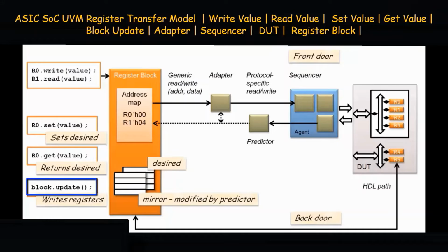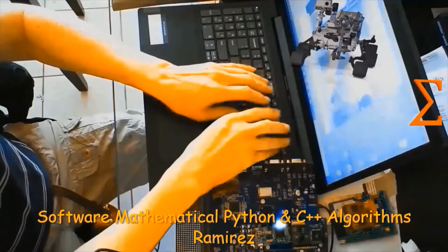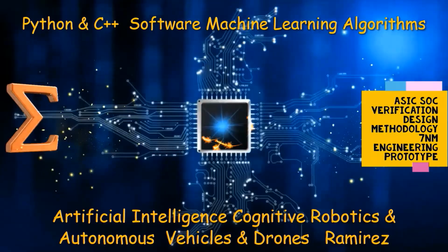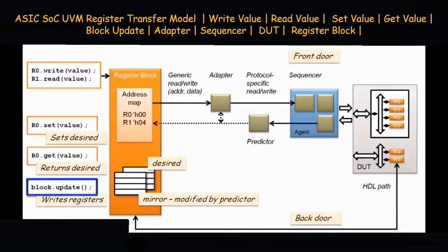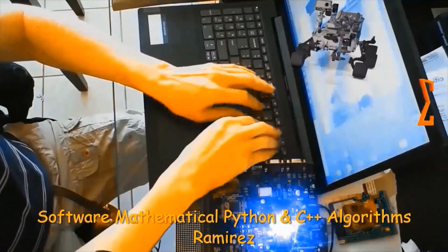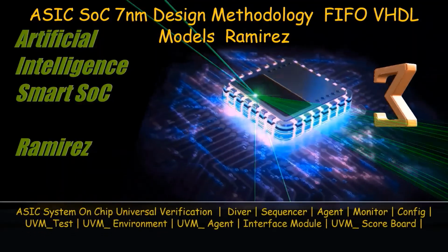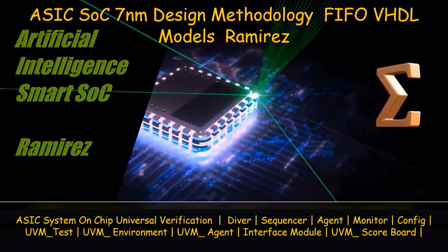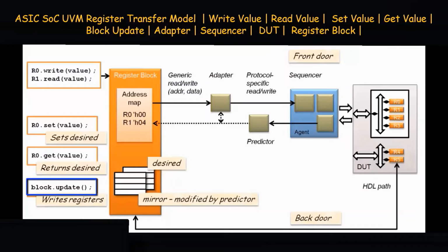As stated before, the register model provides a layer of abstraction, read and write registers, an object instantiated between sequences, scoreboards, and agents that abstracts details of control and status registers in the DUT, permitting sequences and scoreboards to access registers by name.